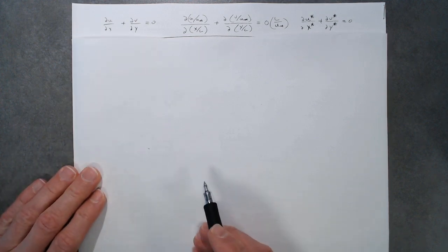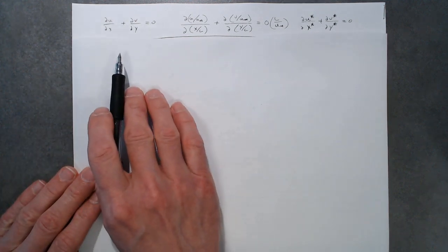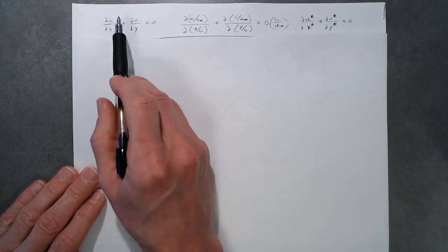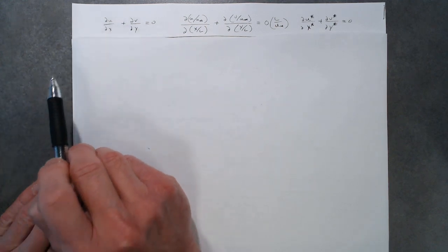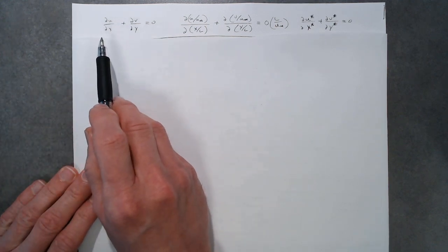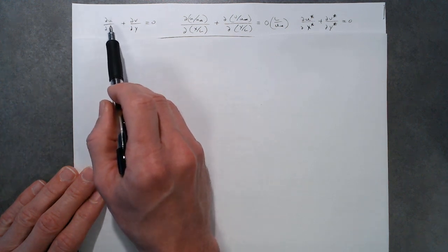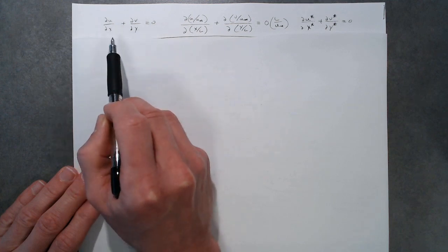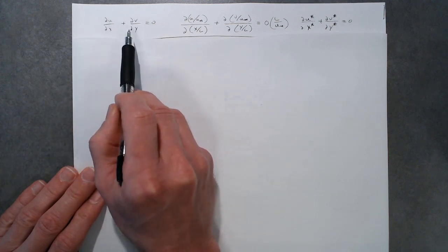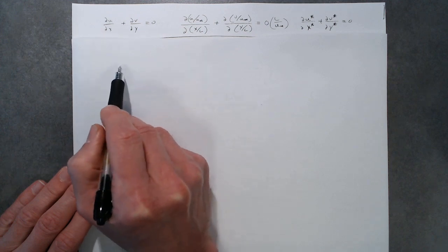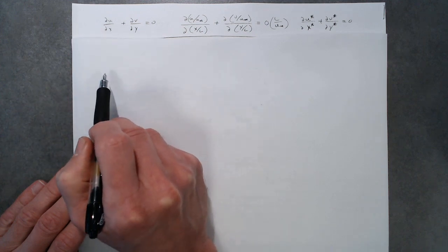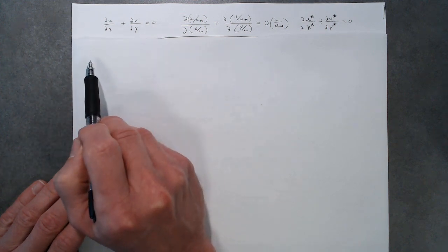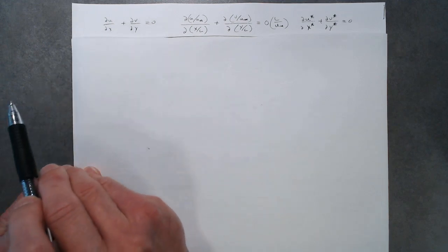So using those normalizations, we can rewrite our boundary layer equations in terms of these non-dimensional variables. And so we'll start with the conservation of volume or conservation of mass, and this is relatively easy. We're just saying that the partial of u with respect to x plus the partial of v with respect to y is equal to 0. Again, we remember that we derived this by saying that the difference in inflow and outflow in the left and right and top and bottom faces have to equal 0 so that we conserve volume in the region of interest.